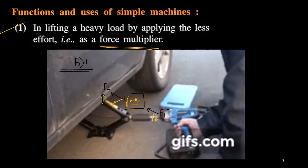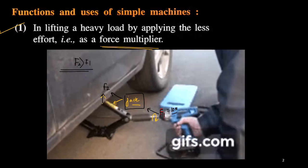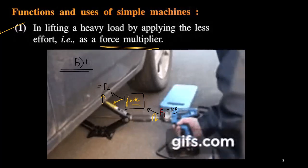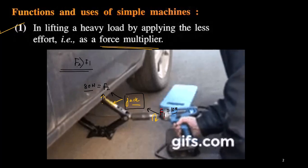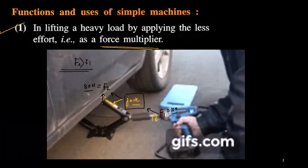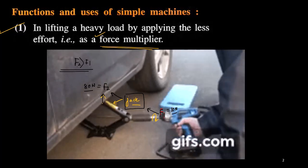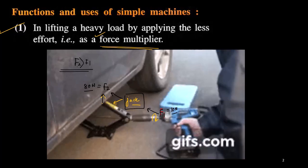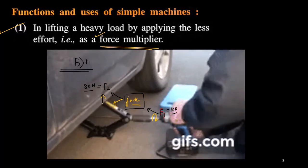Let me give one example. Let us say F1 is 10 Newton, but 10 Newton is not sufficient to raise that load. So let us say I need an F2 value equal to 80 Newton. That means 10 Newton has to be multiplied by 8 so that I can get the 80 Newton value. So this particular device, the jack, is acting as a force multiplier. The force multiplier is one use of the machine, where I am using multiplication. The force has to be multiplied so that the input force is increased.